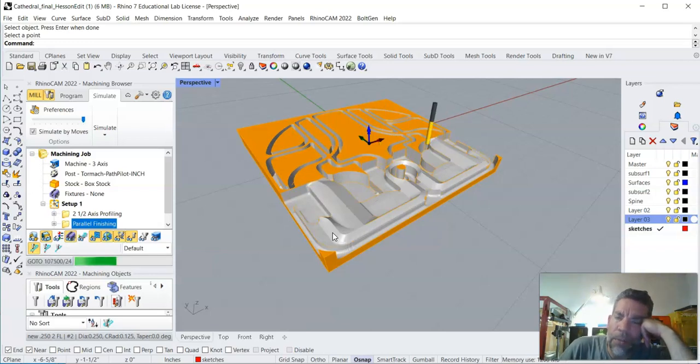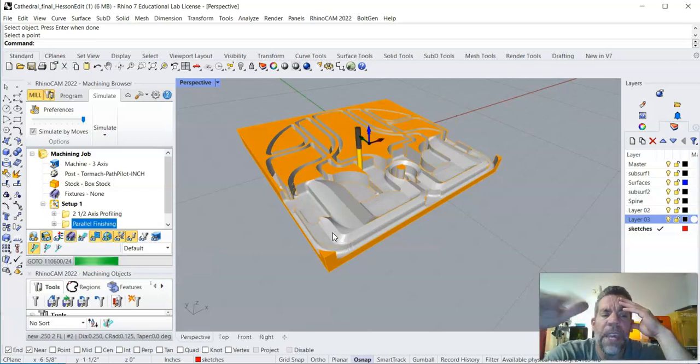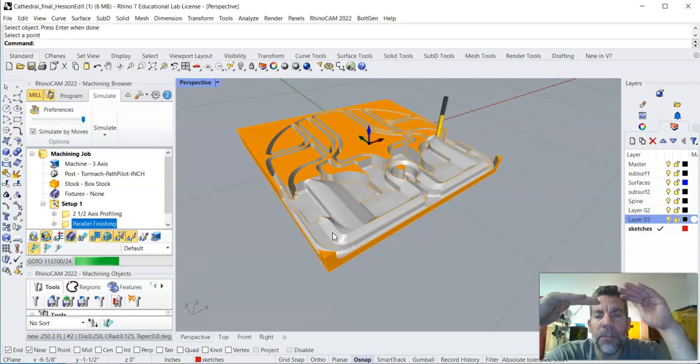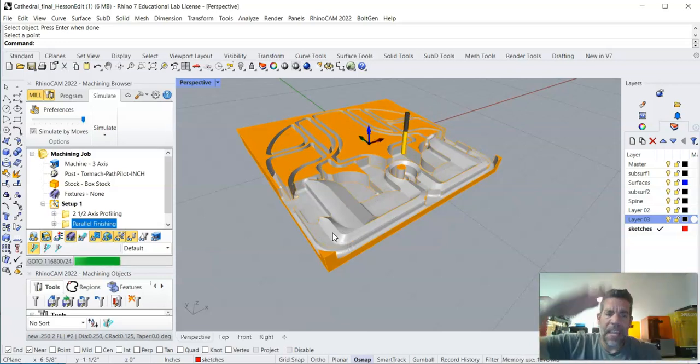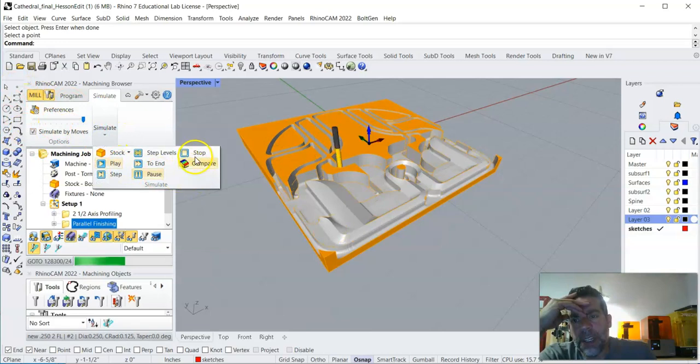mill out things. And even I was looking at your file, and we could have milled out, we could face that section that is where the windows are. We could do a 2D operation, a 2.5 axis operation called facing, where we actually face down to the level of where that model is located. So we could divide this model up into different parts, face the one section, then cut the windows out, and then come back and just do the 3D area only. Okay, and I'm going to show you here in just a second when we get done. Actually, I'll stop this because you get the idea.